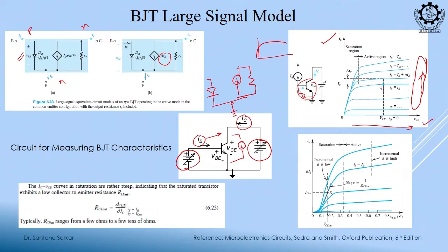on this y axis also IC is having several plots, clear. So, which region you know, if your base voltage is less than cutoff voltage, then it is in cutoff, right, IB and IC are equal to 0, this is cutoff. And when both of the junctions are forward biased, then it is saturation region, and when this base emitter is forward and the collector base is reverse, then this is in active region, right.